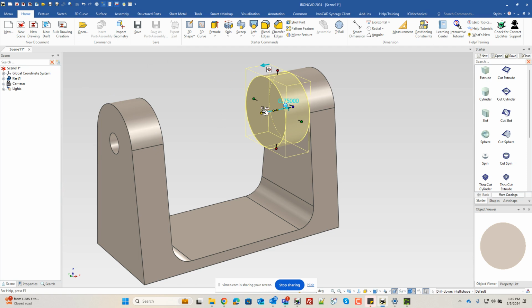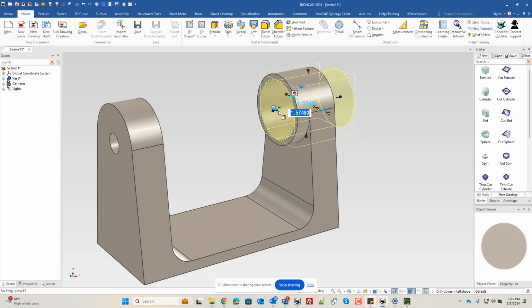Oops. There we go. So that gives us that value. Divide that by 2 because it's going to be the same on the opposite side. So that'll give us our overall value of that. And then we can put our counterbore shape on here, which is actually a diameter of 1.25, and it's got a depth of 0.5 inside of there. So that's that shape there.